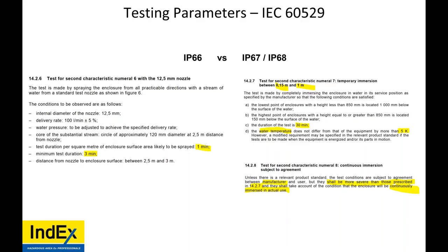Why do our watches have water resistance up to XX meters instead of IP ratings? They do have IP ratings, but okay, so you're talking about atmospheres versus IP ratings. Some, let's say a smartwatch, can go up to IP68. That could be any depth for any period of time, depending on the manufacturer. While IP67, the 7, is up to 1 meter, minimum 15 centimeters, 30 minutes minimum. Further than 10 meters, every 10 meters is an atmosphere.